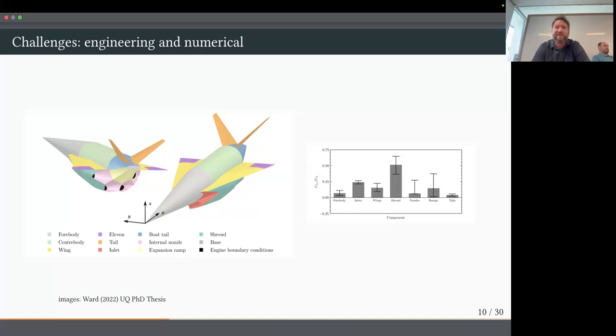And that I don't actually think about during design. It just comes out, and then we have to account for it later on. In fact, you'll even see the inlets provide more lift than the wings. That's not to say that inlets are a great wing shape. That's more just to say that we really don't need big wing planform areas on these vehicles that are flying at this speed. And as we'll conclude the talk today, we're going to see a vehicle with no wings at all, just a pure lifting body.